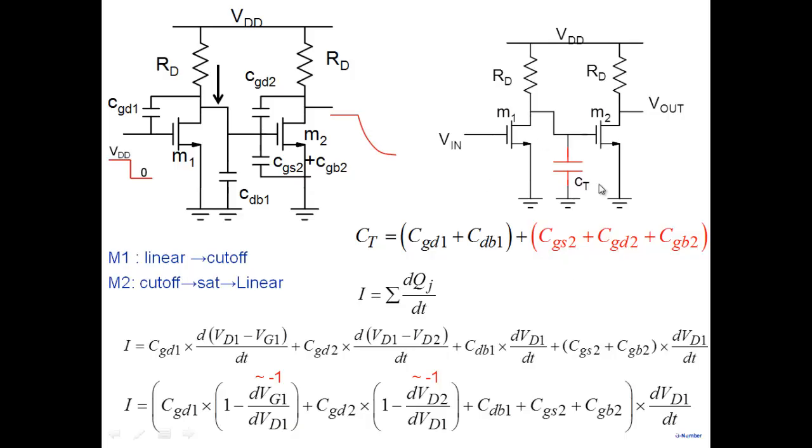So the motivation for this is, once we write it in this particular form and put here -1 and some sort of -1 here, they all add up into one single capacitance times dVD1 by dt. And dVD1 is what? Between this node and the other node, which is ground. So that's how all the capacitors get lumped up in one single place here, CT. Okay.